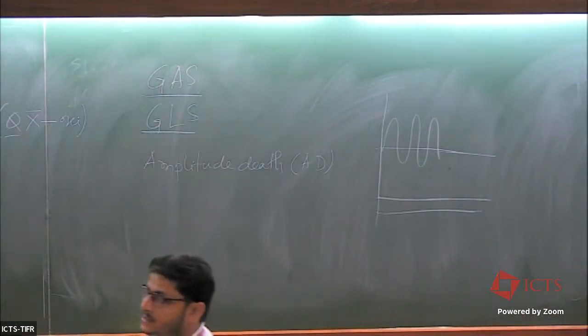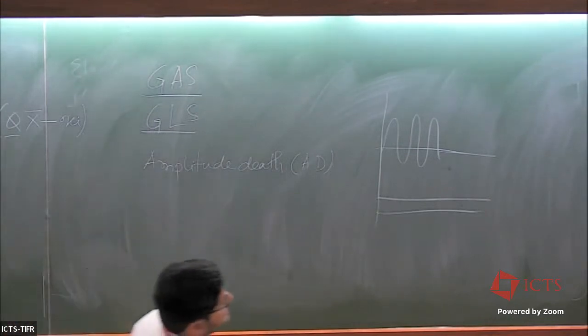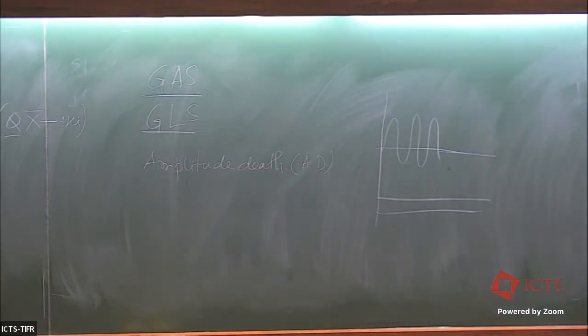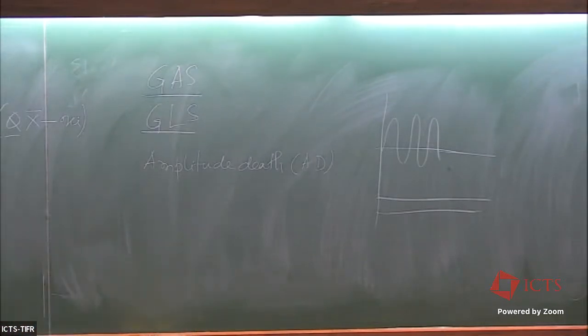Up to there, any question? Yes, obviously. That V function, you can find in some papers or books on the Krasovsky-Lyapunov theorem. They have given a theorem, and from that theorem we consider a positive definite functional like that. This positive definite functional must be negative along the trajectory of the error equation, and that may give rise to the condition for stable synchronization.